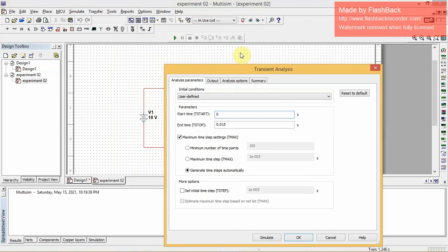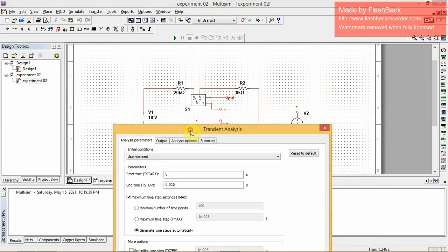When you define the stopping criterion, you have to consider both the charging and the discharging times. So your stopping time should be at least the sum of your charging and discharging times. Meaning if your RC constant times 5 for charging is 1 second, and your RC constant times 5 for discharging is 1 second, then your stopping time should be 2 seconds.